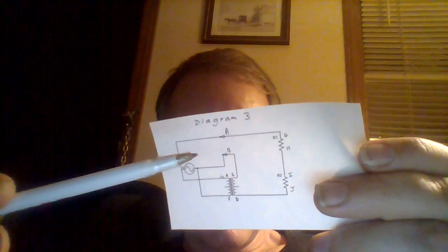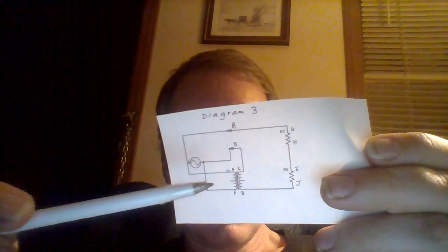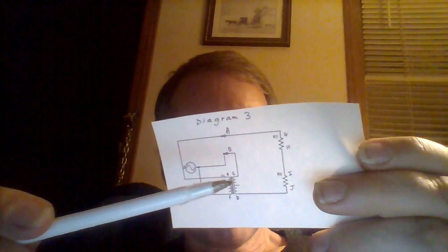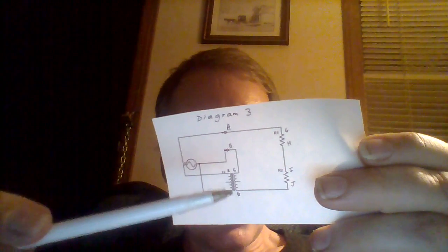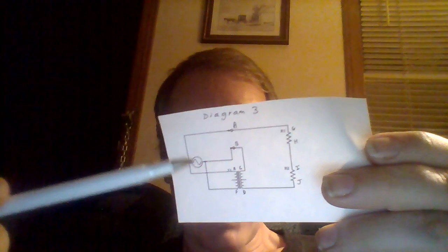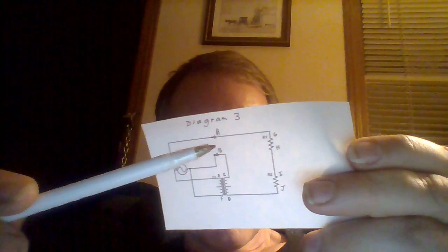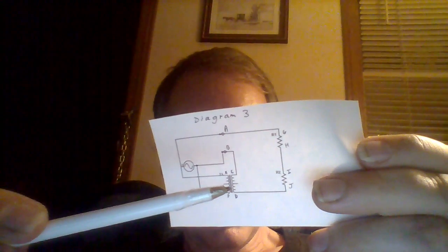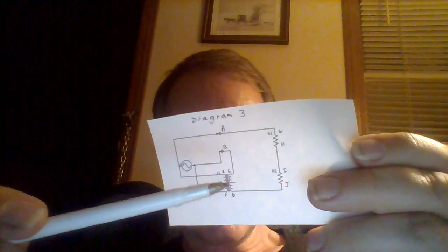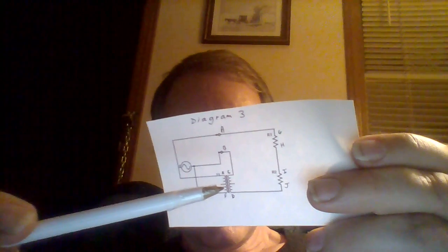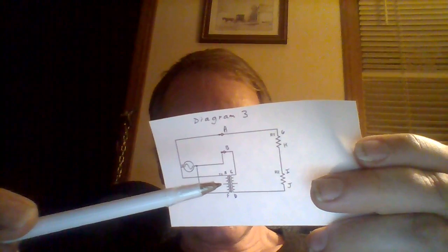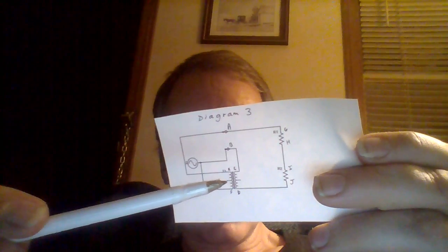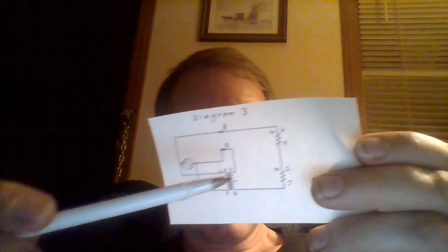So now, like I was saying before, if a circuit could think, it would think, oh, there's two sources of electricity here. One is A and B and one is C and D. Okay, like two batteries in a flashlight. Okay, 120 volts here, 120 volts there. And that's the one-to-one ratio transformer I was talking about. These lines in the middle here are for center tap, but just ignore those for now. But I'll be showing you how to use that in diagram 5.